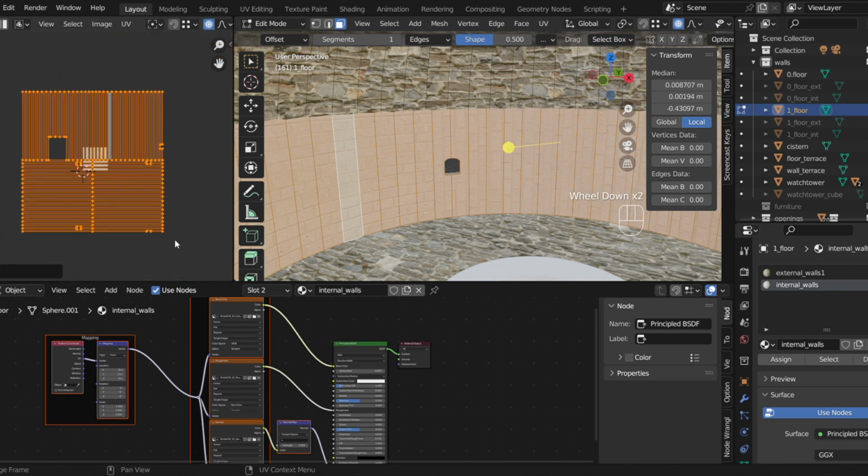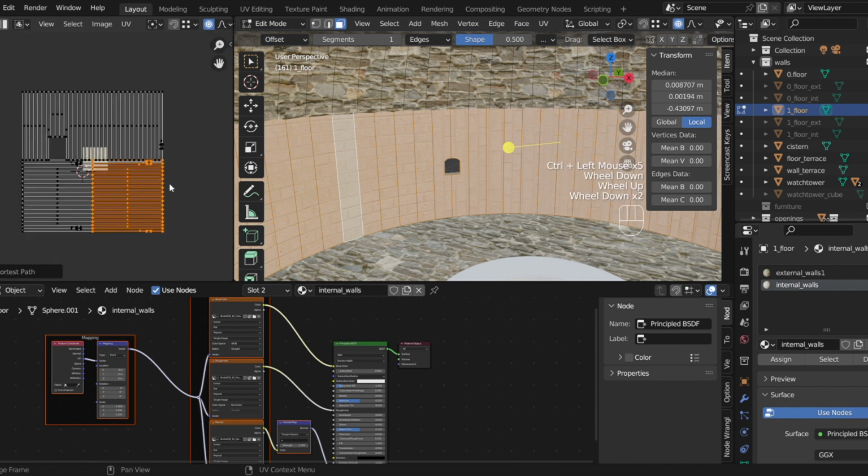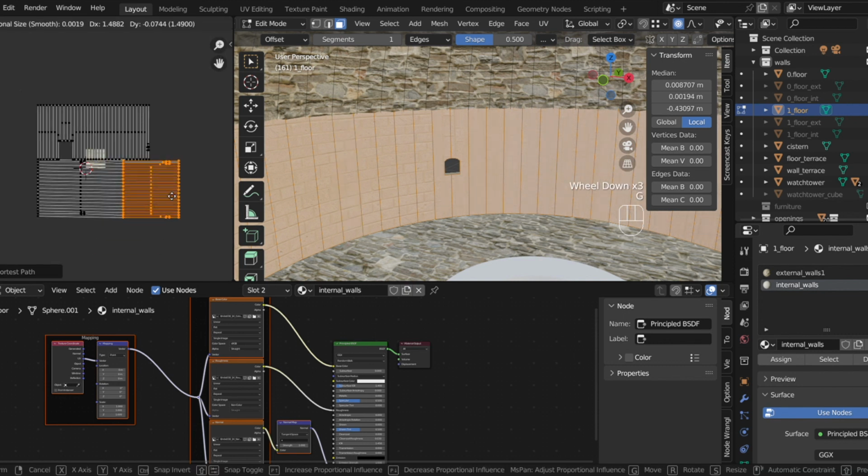We select individual faces and move them around. Due to the fact that the vertices are overlapping, we will also move the other unselected faces. Therefore, we select only the portion where we notice a different orientation of the texture, move it, rotate it 19 degrees, and merge it with the remaining portion.